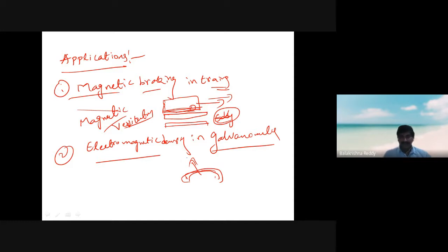The moment the current is reduced, whatever metal piece or soft iron core it is connected to, the eddy currents developed in it act in the opposite direction. So the needle will move in the opposite direction within a short span of time, because the currents developing here are opposite to the applied magnetic field. So it comes back. Therefore, the electromagnetic damping effect acts due to the eddy currents. This is because of the solid magnetic material you are using inside the galvanometer as a core part.